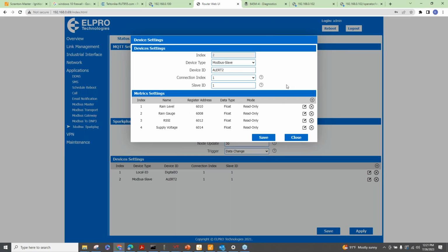And then what it does within it, because this radio is an IoT gateway, it has the Modbus master built into it. It'll pull the slave nodes and put it in registers for you, and actually the actual tag names.